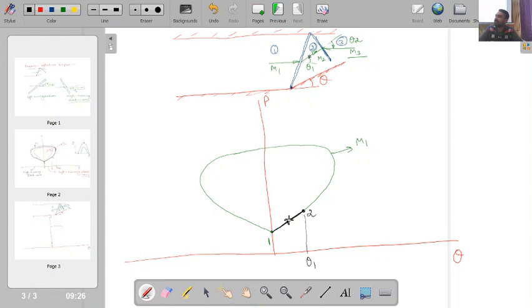Now if you see this point 2, which is already at an angle theta 1, it is now becoming the incident streamline for this reflected shock wave. As it becomes the upstream streamline, our angle will now be measured with reference to this particular line.